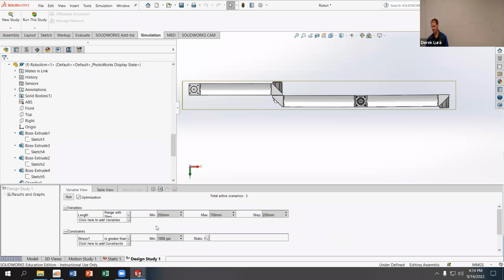We don't have enough time to really go into this in detail. I do want to make an explicit point that right now, I'm not setting these values, but you'll notice that it goes from 250 to 750. It's currently 500 and a step size of 250. That step size is too big because it's only giving me 3 steps. So I'm going to change that to 100.